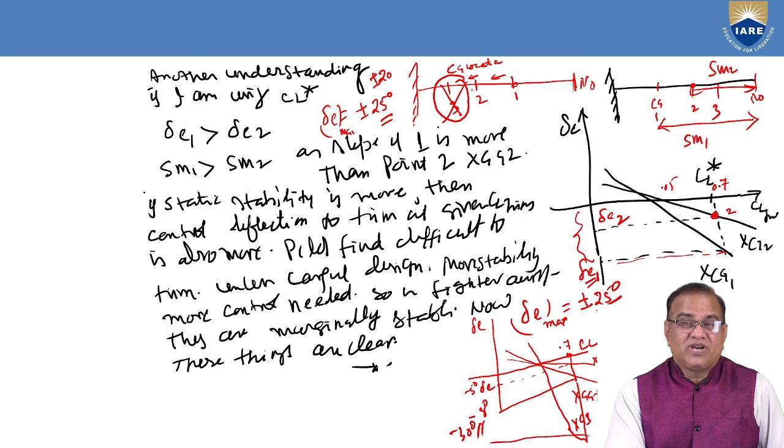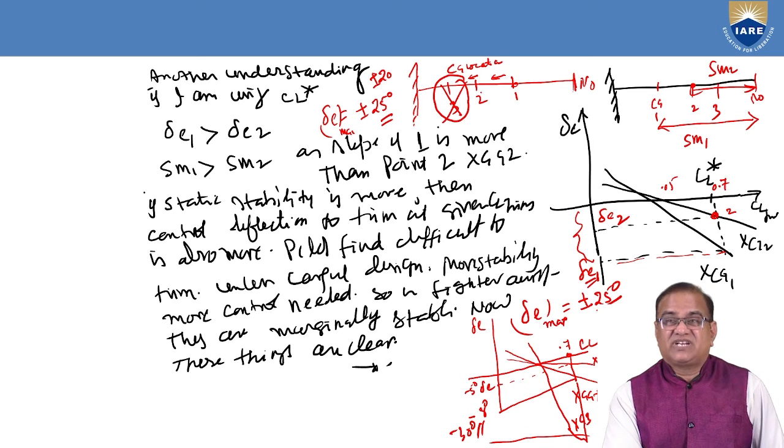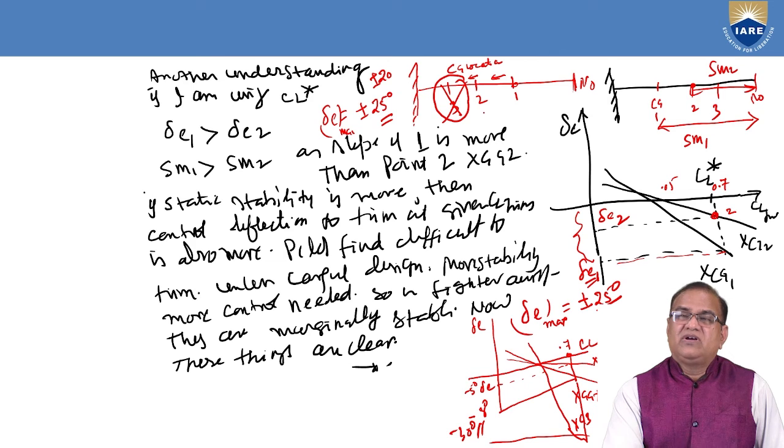So the forward location of the center of gravity is restricted by the available deflection of the elevator, and the aft location of the center of gravity is limited by the neutral point. The center of gravity should fall somewhere between these two limits, and only then will the elevator effectiveness be present.